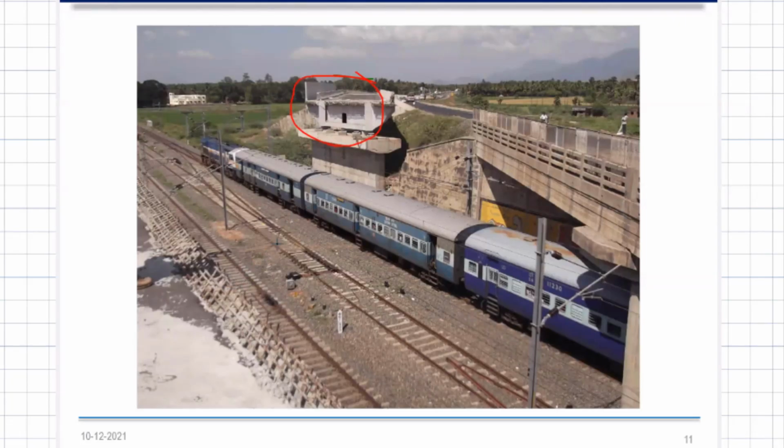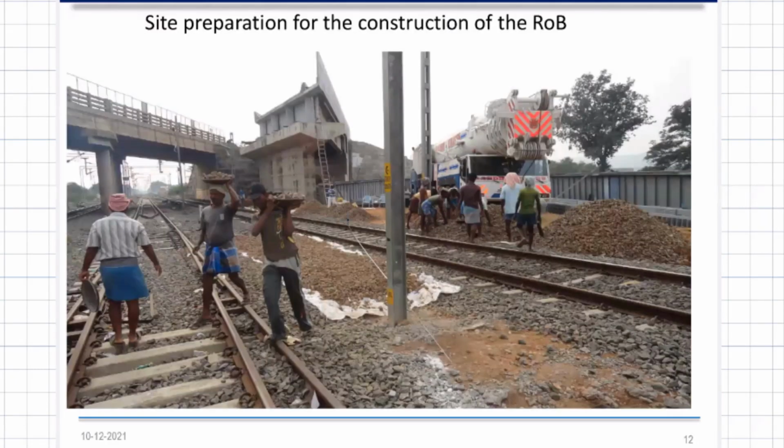Now, what I cannot do is put all the scaffoldings and everything, because it may take 10 days. You can complete it, but it is not about the 10 days; the blockage will cause crores of loss to the railways, right? So it is a busy route, absolutely no possibility. So what we are going to do is get what is called a line block, right? The line block is where you ask the railways, and they will give you a lean time. Okay, take 8 hours, right?